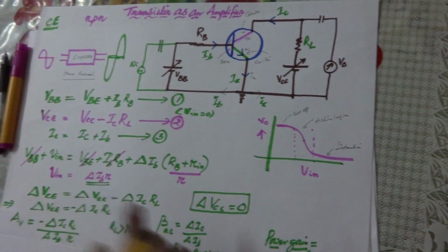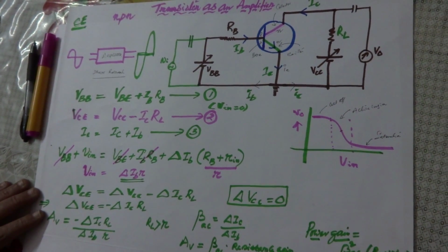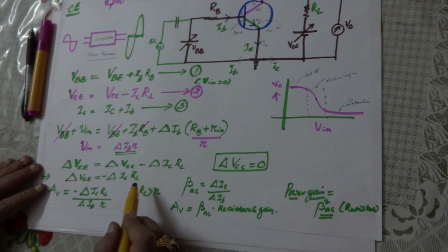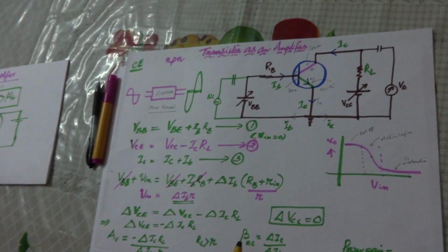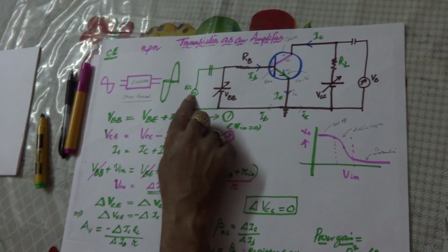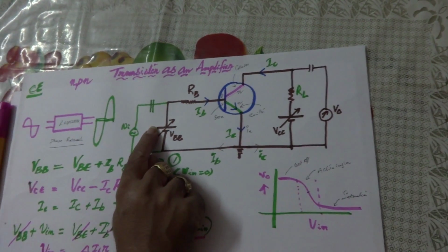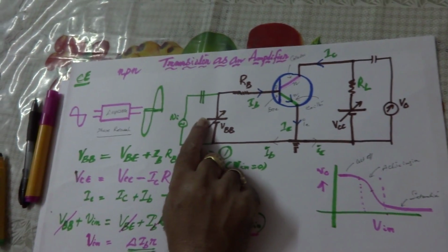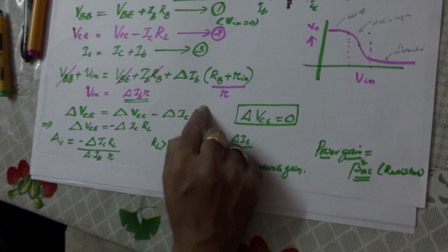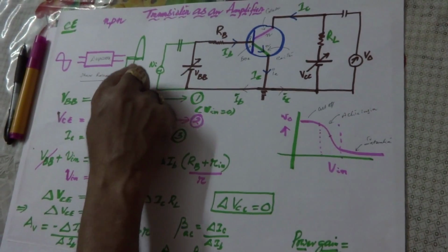of the signals. Now we can explain the phase reversal in a different way. So we know that this is phase reversal. Now if we take this one, we can explain like this. Suppose if positive cycle comes here, then this becomes more forward, because more positive, more potential difference, more forward, more IE, more IC, then larger value is to be subtracted from this delta VCE. That means the value of output is decreased, therefore the negative cycle is accepted.